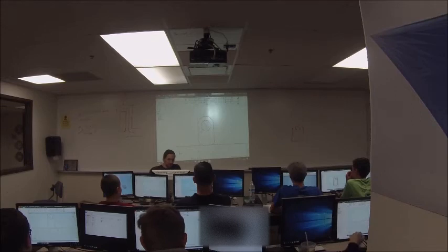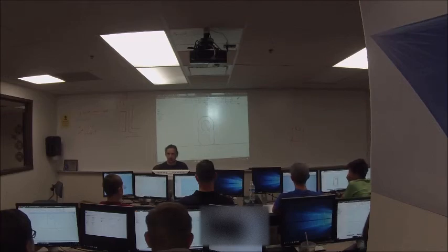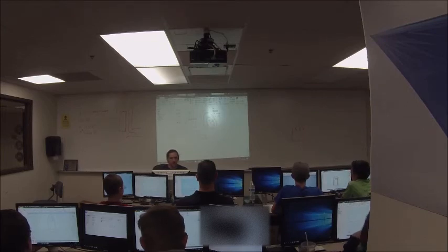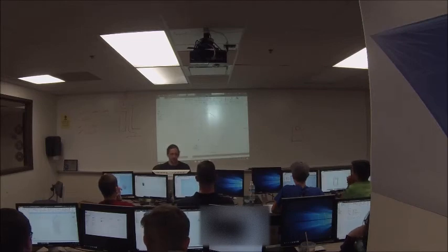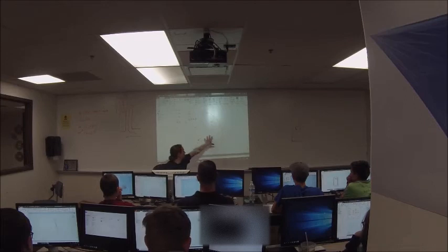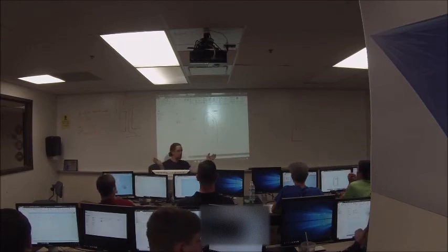I want to show you something that we kind of hinted at last week, but didn't really get into a whole lot. Finish the sketch and click the Extrude Tool. Now you'll notice, I'm going to create a new part here real quick just to show you the difference. If I just have a circle like we were doing last week, 2 inches in diameter, I hit the Extrude Tool and you see immediately it starts showing me 3D geometry. But if I do that over here, click the Extrude Tool, you'll notice no 3D geometry.